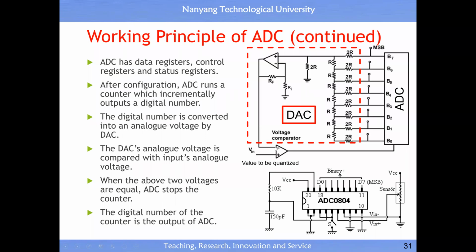Then you do the comparison. That gives you the feeling that you instantly get the right prediction, because 1 million predictions per second is a huge amount of predictions. So it gives you the impression that once you have an analog input, you instantly get the right prediction. All right, so this is the working principle, very simple. This is why the microcontroller is so cheap, right?